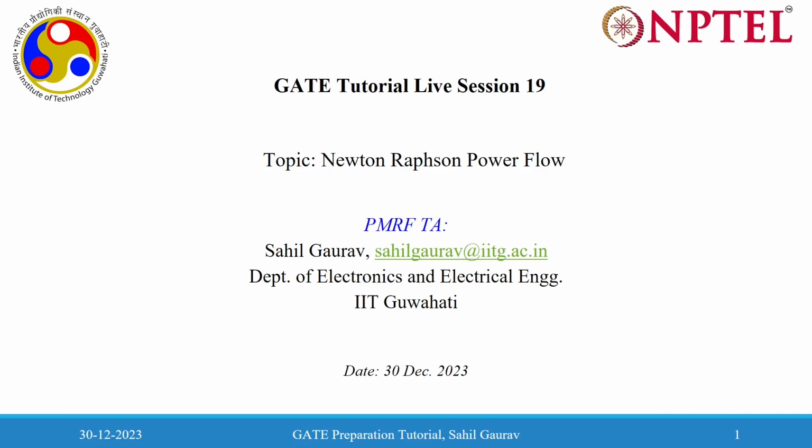In the previous session 18, we discussed the Gauss-Seidel load flow method, an iterative approach to solve nonlinear equations. The Gauss-Seidel load flow method has linear convergence characteristics. It usually takes more time to converge if the system is large or big. It may not converge in some conditions also. Therefore, we go for another iterative approach to solve load flow equations, that is the Newton-Raphson load flow method. Today we are going to discuss this.